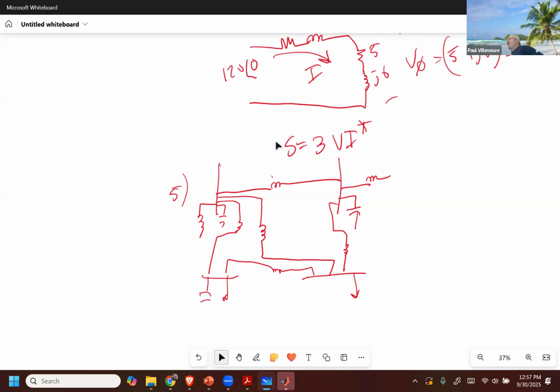Well, the first thing you do is I'm trying to build Y bus. So the loads here and here are not part of Y bus. Those are just loads, not part of the system. Those are interconnected loads. So in terms of affecting Y bus, they have zero impact, none whatsoever. So you can throw those away. They have nothing to do with anything.